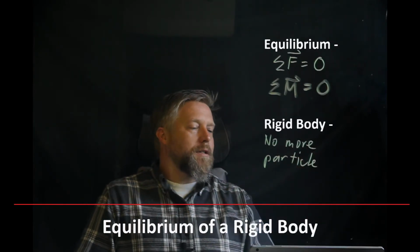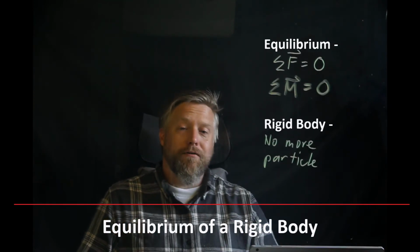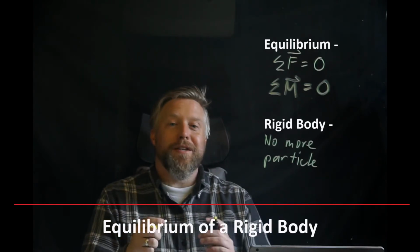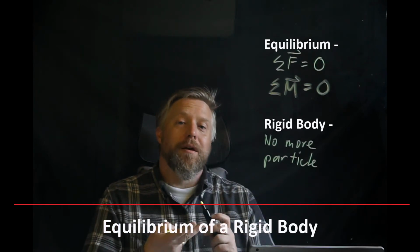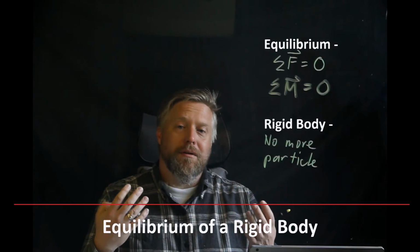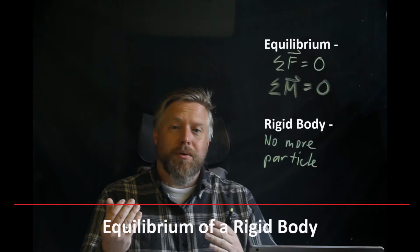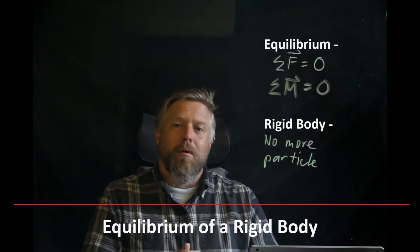Okay, so our particle assumption is gone, which means we have to draw the full body and we have to draw forces where they're acting. We also sneak one more thing in there. Up to this point, we have basically told you where the forces are acting, except for weight and ropes. You have already used your knowledge of physical situations to put the weight in the center of gravity, and you've used the fact that ropes cannot push to change a rope that's connected to something to a force. We want to build on that.